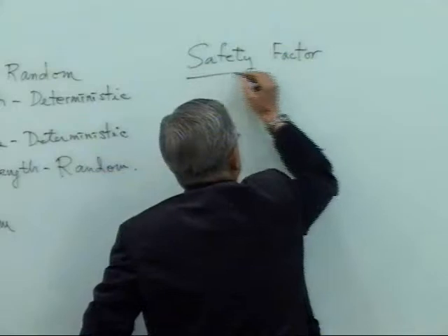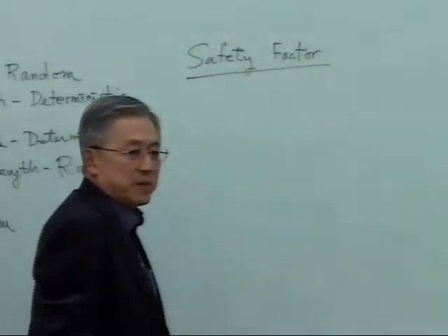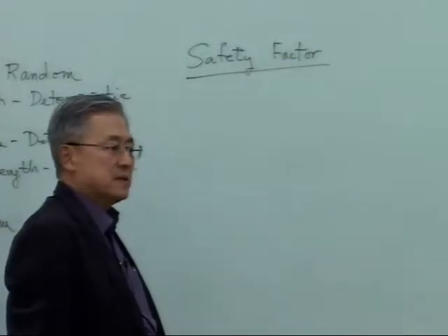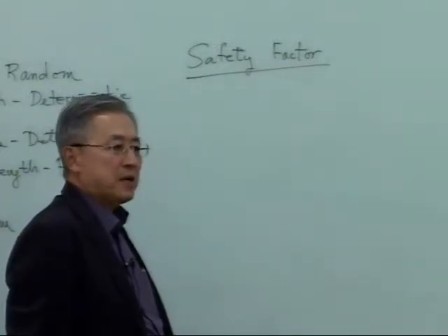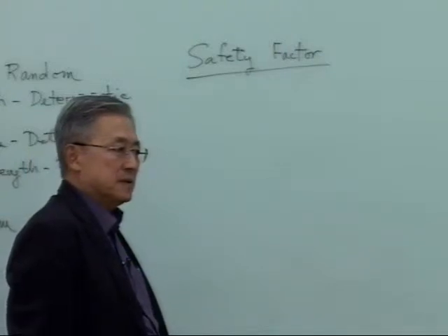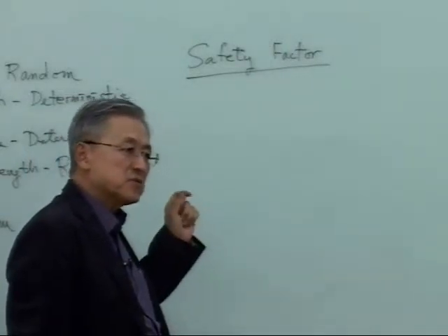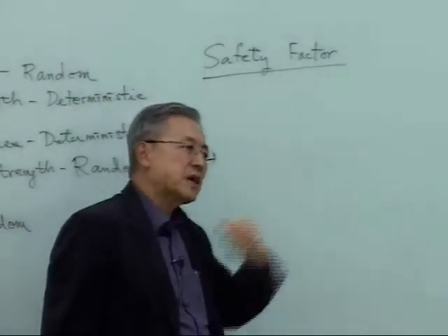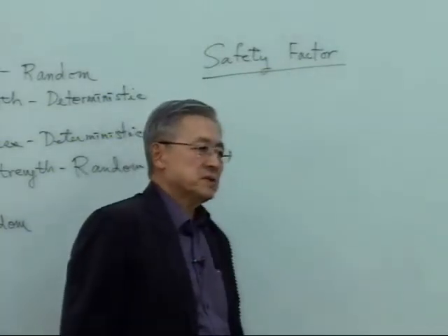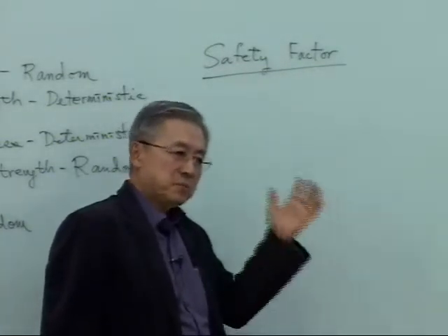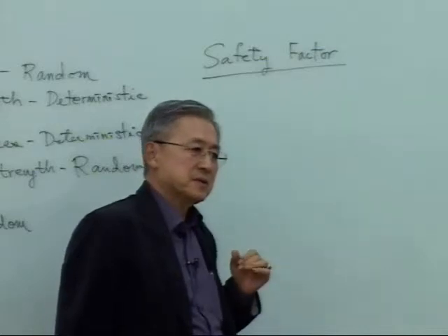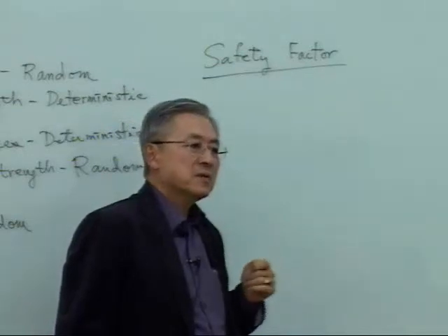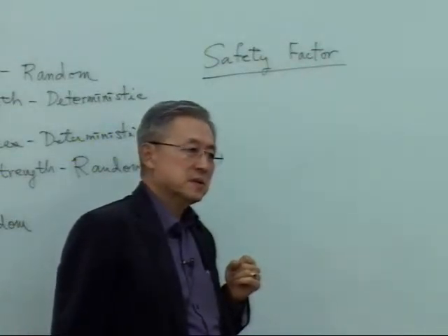If you look at the vendor's spec or design spec or ship building manual, you will see the desired safety factor. Safety factor did not just come from some designer's mind. The background is reliability. Safety factor and reliability are supposed to have a one-to-one relation.